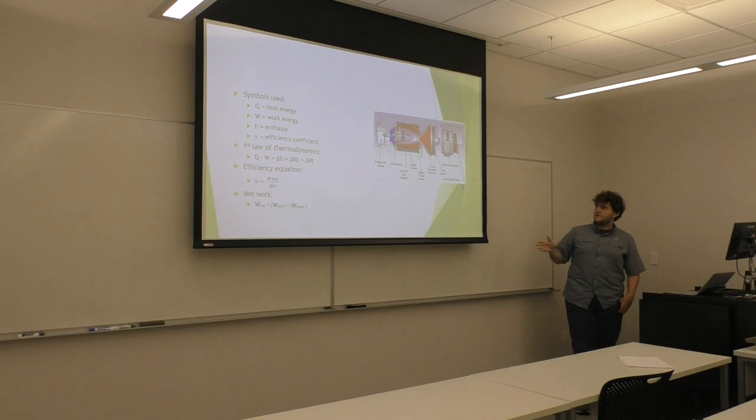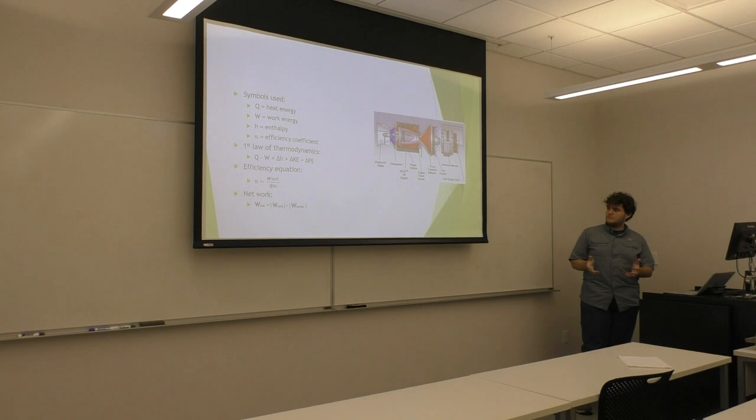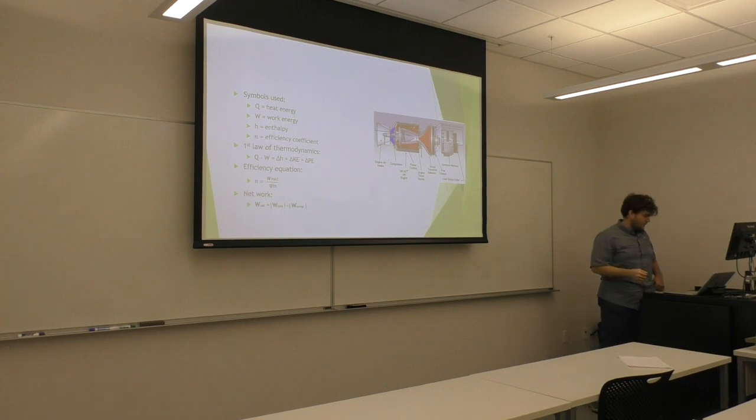Kinetic energy might change, but since the mass flow stays relatively the same throughout the system, it would only change based off the area of the inlet versus the area of the outlet. We would be finding the efficiency of both the first turbine within the engine and the second turbine that drives the alternator. That's why I have the efficiency equation.